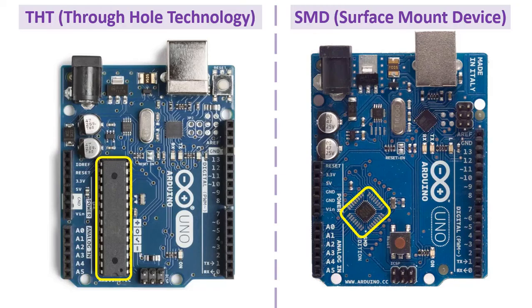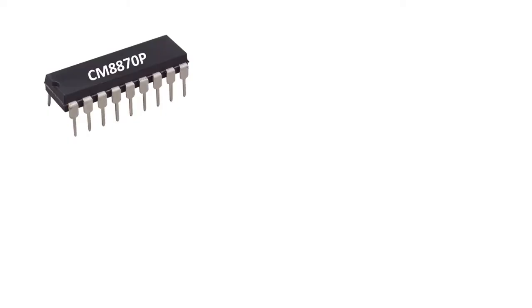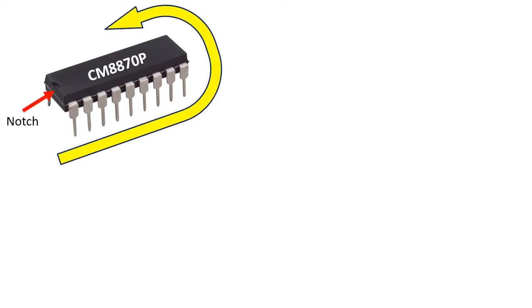Now let's look at how the pins of the integrated circuits are numbered. When we hold it to read the text on the IC, there is a notch on the left side. Pin names are numbered starting from this notch. This is the integrated 18 pins we reviewed.